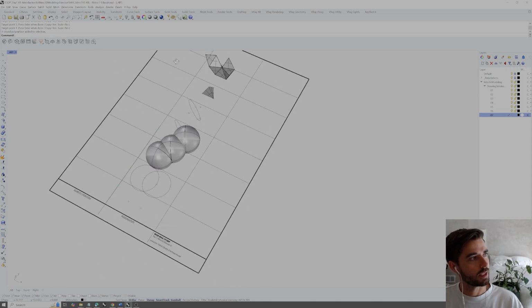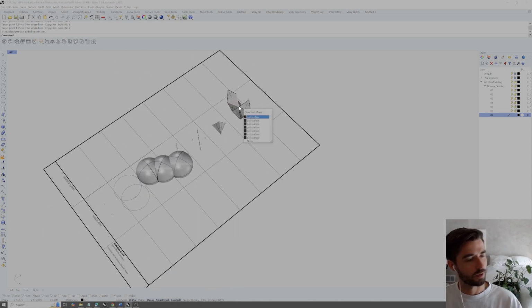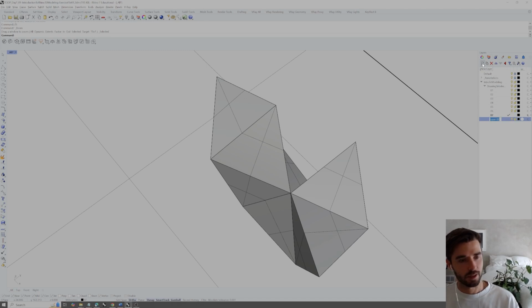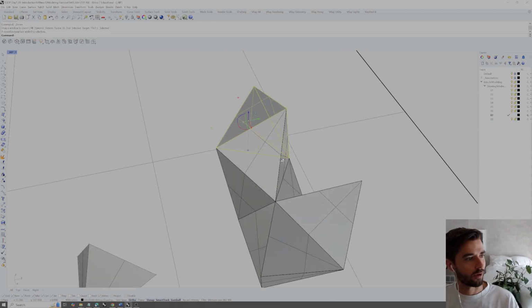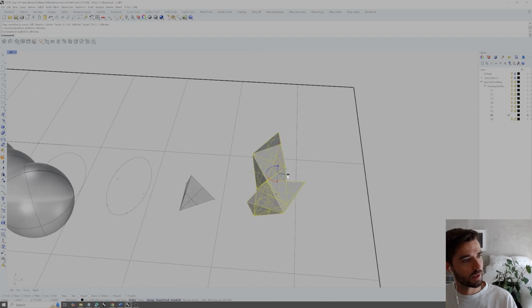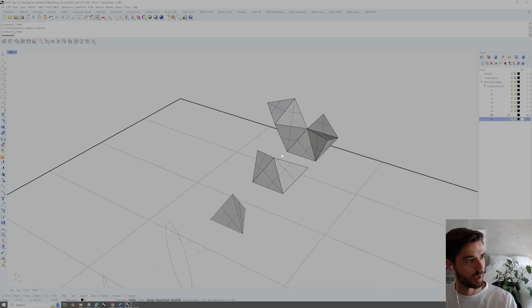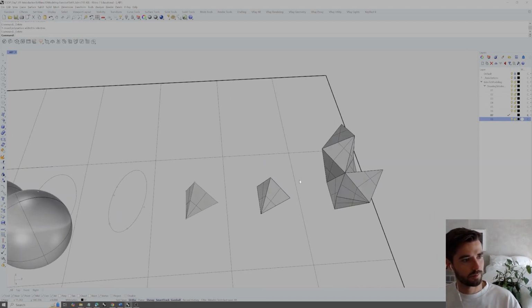So we didn't need, I guess, that last one, or maybe what we can do is zoom in and we can say that's going to be layer 8, and we can take our assembly, copy it up, change that to layer 8 there, and then just delete these so that we just have our base tetrahedron. Great.